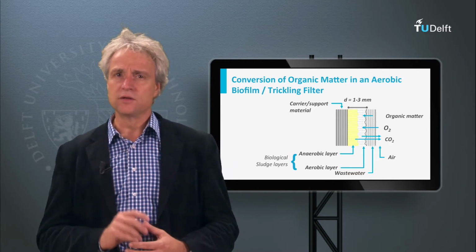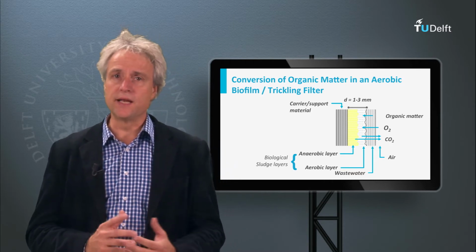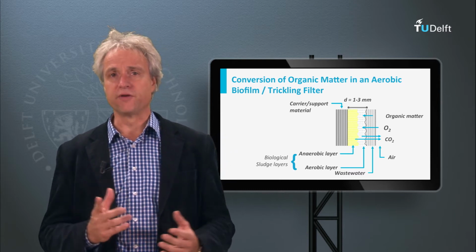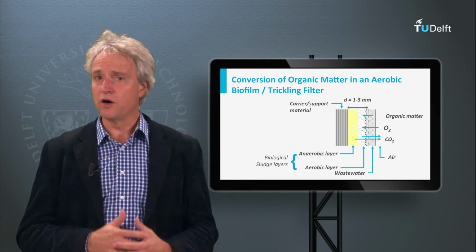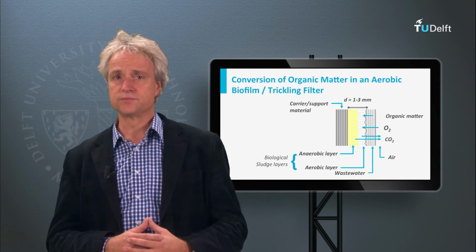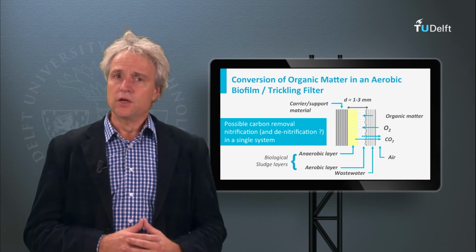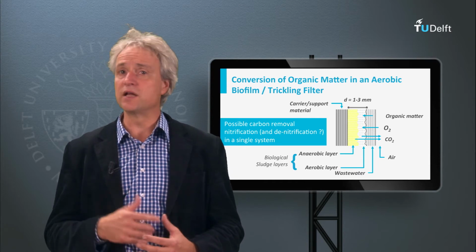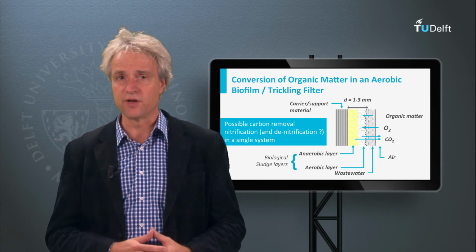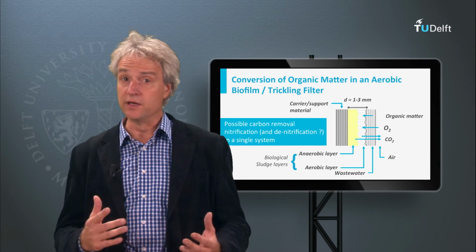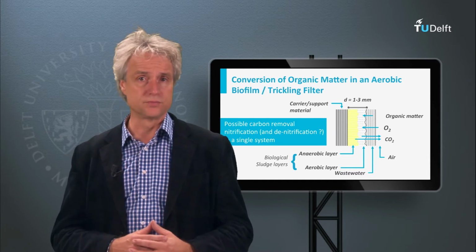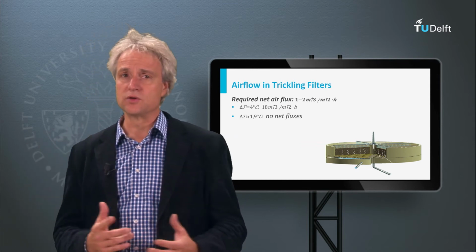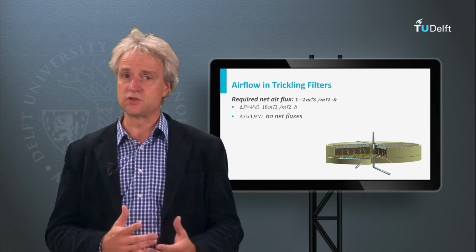Also deeper in the bed towards the filter floor, oxygen can be limited owing to the high biological activity at the top. Proper venting or air supply is therefore of utmost importance in the trickling filter. However, under low to moderate loading conditions, the bacteria that oxidize sulfides to sulfate and ammonium to nitrite or nitrate may also develop in the biofilms of the filter, leading to full BOD removal. Adequate oxygen supply is considered the most important aspect of a trickling filter design for sewage treatment.